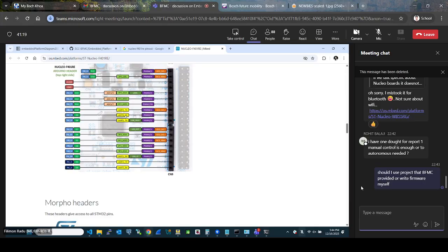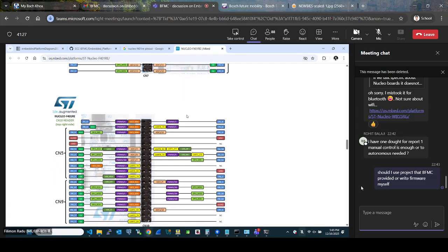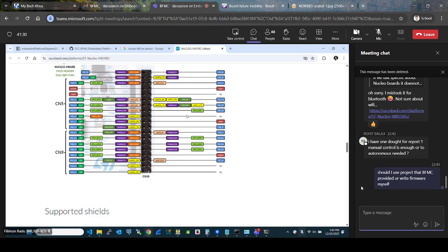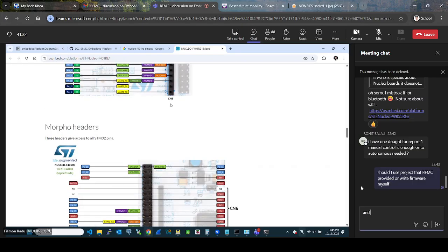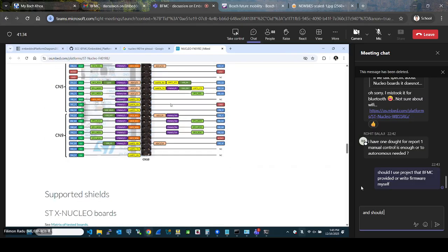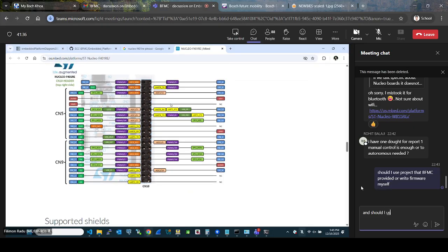We have to look for RX, TX, receiver and transmitter. I think it's possible, but make sure you don't use the same UART communication as the USB is using. I think it's a trial and error process. Try all the UART ports.